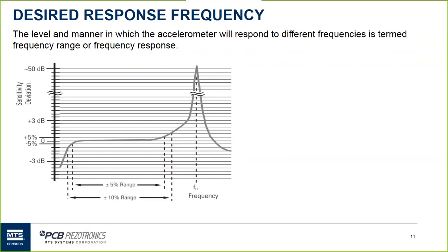When you're operating above that or below that, you can have errors introduced into the sensitivity, producing errors in your measurement chain. Those are typically provided in calibration data reports, so you can understand how frequencies out beyond the linear zone affect that measurement and accuracy, and even below as well. So I just want to make sure I tied it all together into one plot to allow you to look at effects of low frequency response and high frequency response of a typical accelerometer.